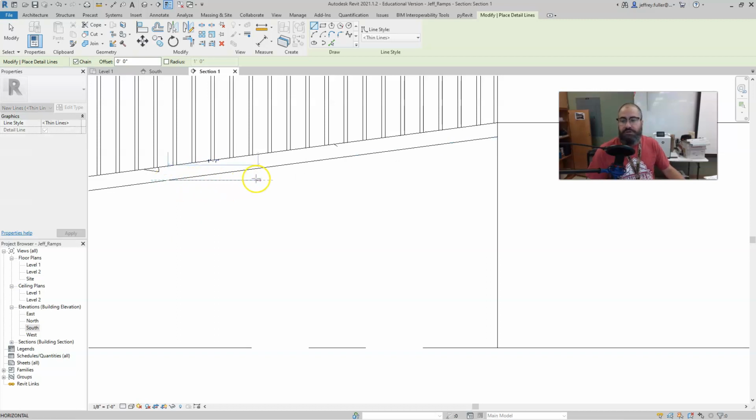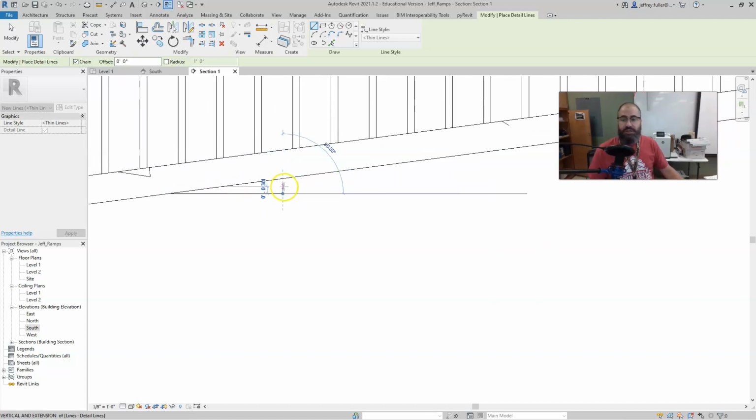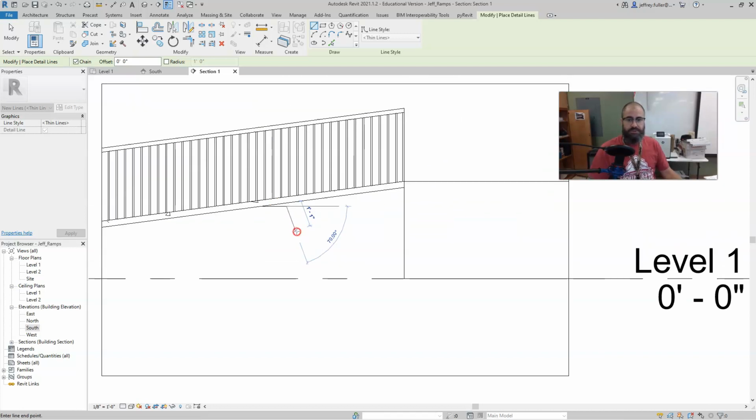Okay, I'm going to draw 12 inches this way. So this is where it's almost just like doing rise over run. So I need to get 1 inch from there to the ramp. I'm over 1 inch, so I am beyond code. It's up too high. So I would really need to make this ramp a little bit longer to reach the 4-foot height. And of course, that might just require me deleting the ramp and drawing a whole new one.